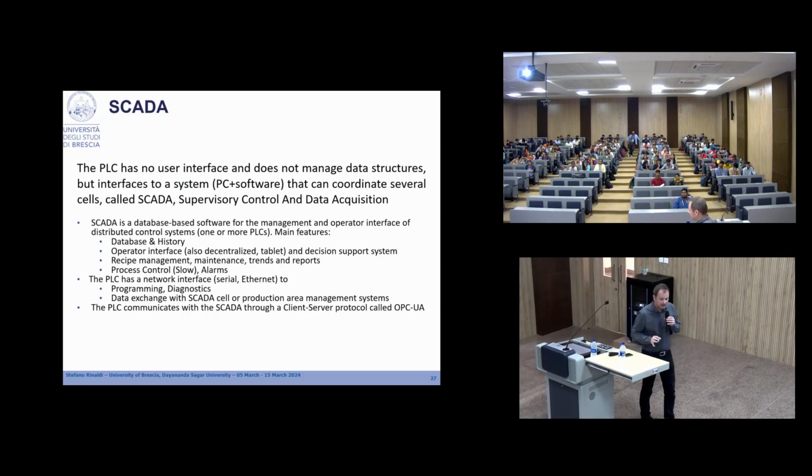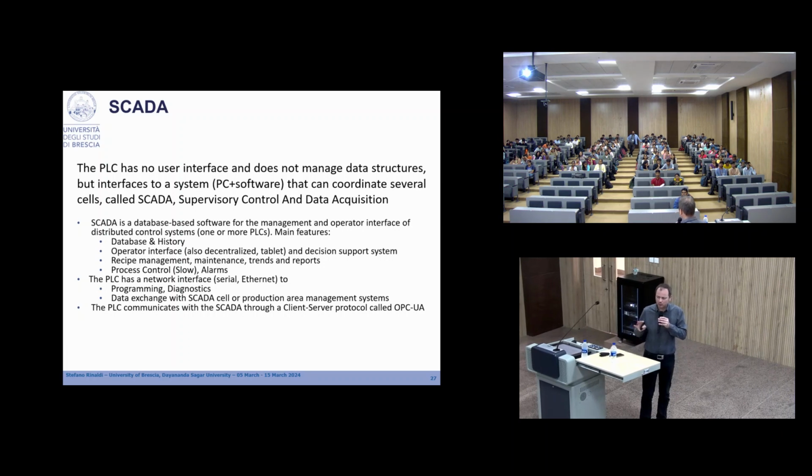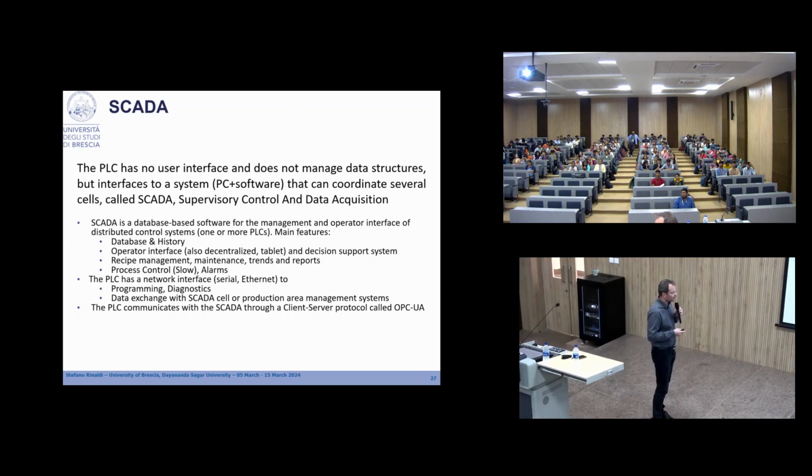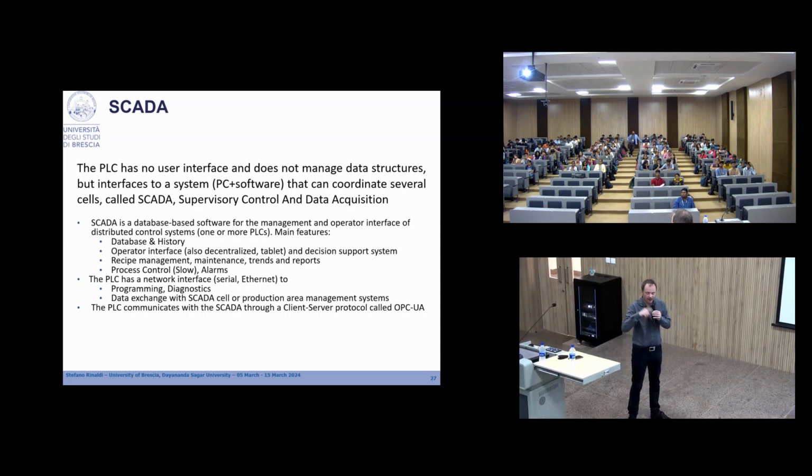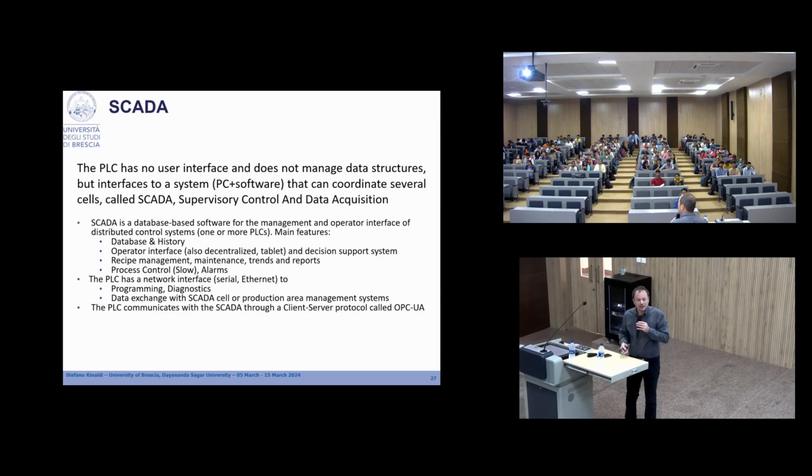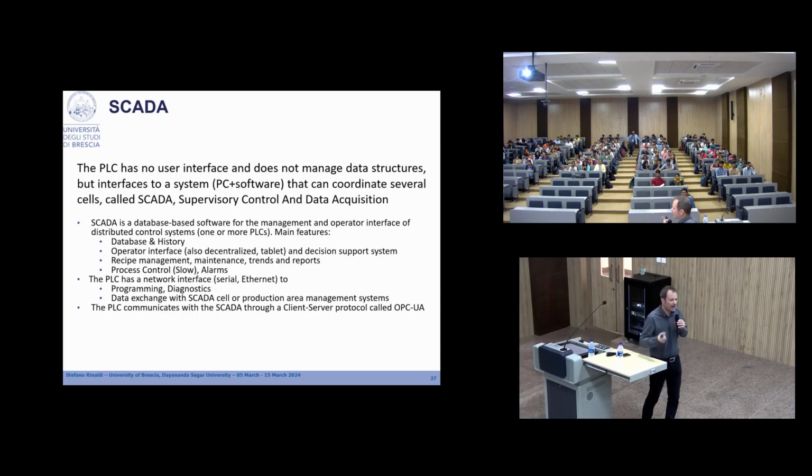A SCADA system can be used also for some type of control, but generally, as I showed you in the pyramid, the control functionality is generally performed only by the controller, by the PLC. The role of a SCADA is mainly to supervise this kind of controller.